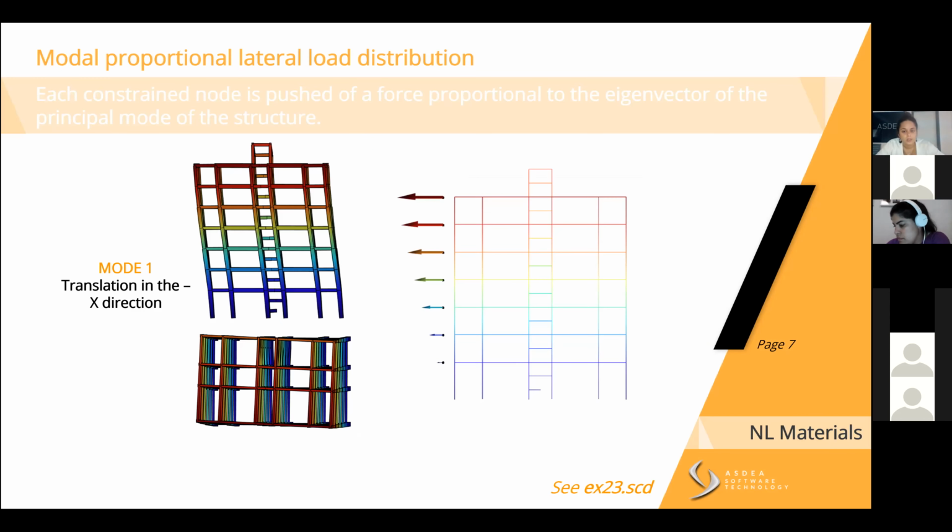Yes, lateral load, lateral force distribution. In this case, we don't yet have explicit tools, X-objects, that you find in the tree to do this, but it's possible through TCL scripting. We're planning to develop this TCL scripting into some X-objects that you will be able to just pick from the tree and add to your analysis as specific load patterns. But in general, it's already doable. You just need to know how to code it.